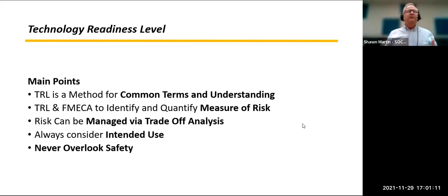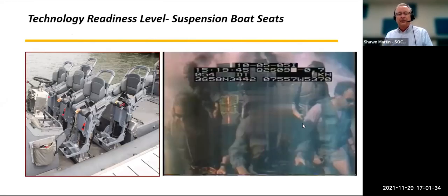Yeah, well, when I use the word refined, I mean matured, right? Additional engineering has been put into it, refining the design for durability, reliability. On some systems it could be electromagnetic interference from a radio system or another electronic component. It could be corrosion. For example, those boat seats right there: we did EMI testing because the radios would actually affect the electronic controls of the suspension.